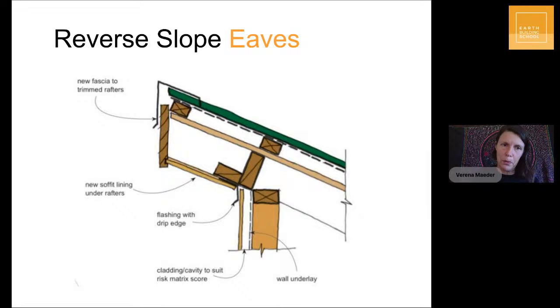Same thing at the top of the building, the very top. You see the black line that sort of protects the very top of the roof where there's a material change from your roofing iron to your fascia board. So everywhere where you have material changes, you have gaps, and you need to apply these flashings for water to keep out of your construction.